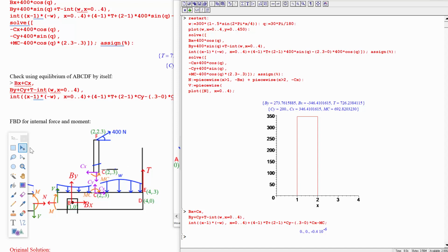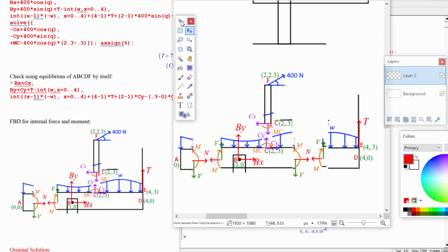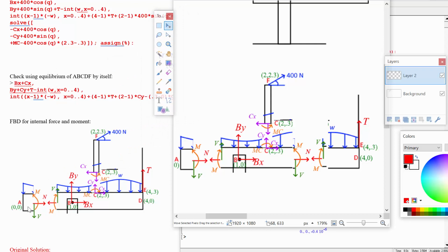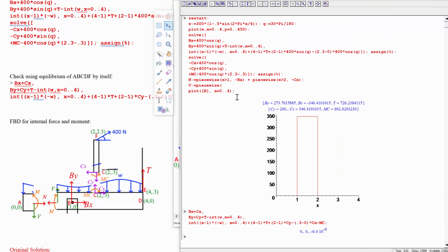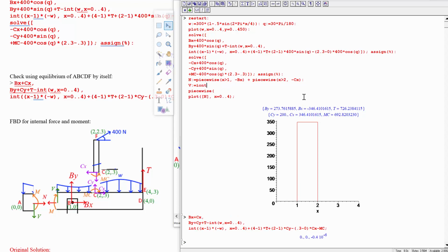So let's see. When do we have shear force added? V is going to be adding up the total W that's happened so far and has to oppose that. So that means that we're going to take first the integral of W from x is 0 to x, up to the point that we're at, but we have to oppose that. So the integral of negative W from x is 0 up to x.